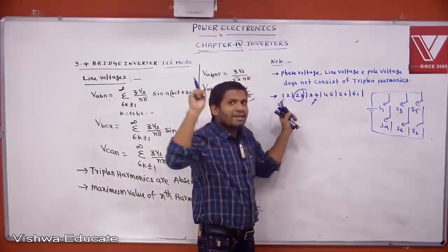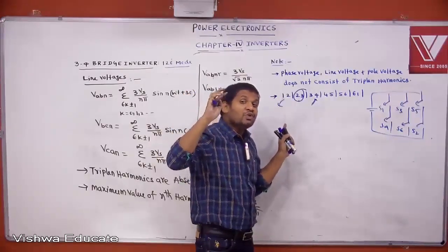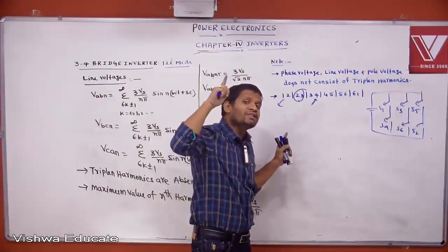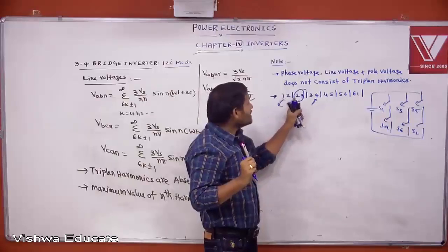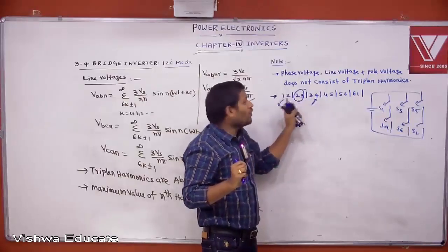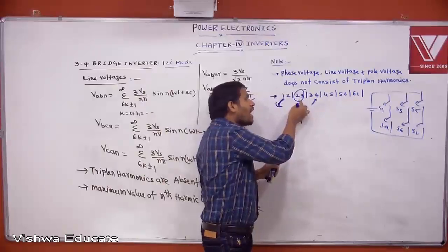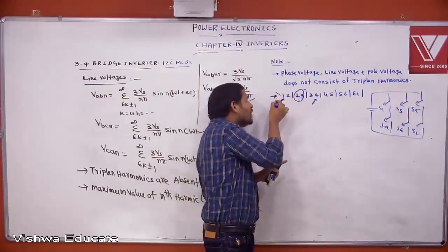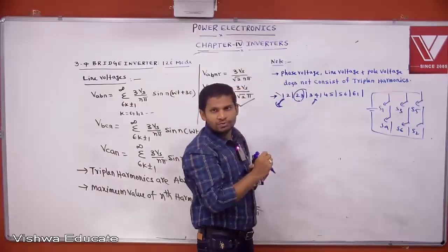But that is not the case in the 180-degree mode. That I explained now. That means there is no phase difference, 2 switches in one leg in 180-degree mode, hence there is a possibility of shoot-through fault. But in 120-degree mode there exists a 60-degree phase difference. 1 and 4 are on the same leg. 1 is turned off here, but 4 is not turned on here. After 60 degrees only 4 is on. Even though there exists a commutation failure of 1, 3 is only on.